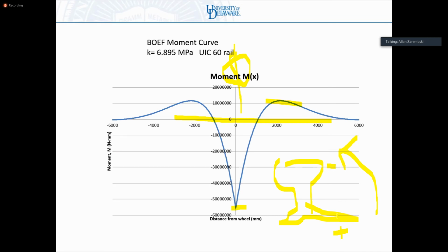What that means is I'm getting reverse stress, which means I have a potential for fatigue. And it's more than a potential fatigue, as I will spend a lot of time on it. This is one of the causes of rail fatigue. This is one of the contributing factors to rail fatigue, which is a major issue and one of the most major failure modes in rail, and cause of derailments and failure and rail replacement and all sorts of good things like that. And to understand that, you have to understand this moment reversal.